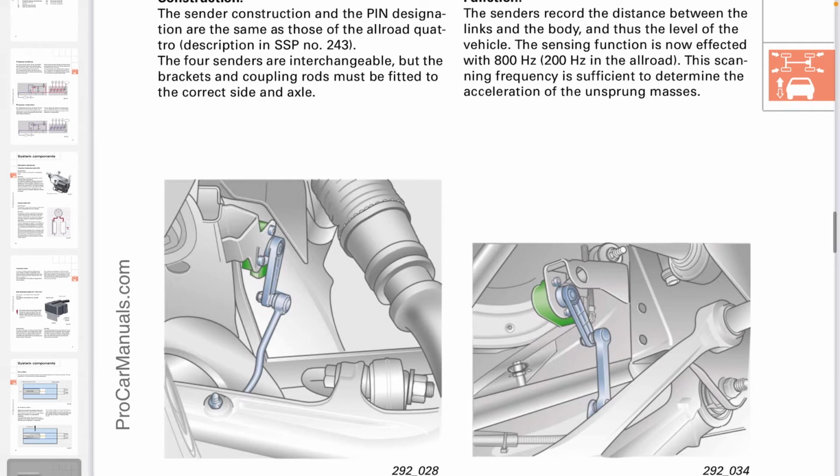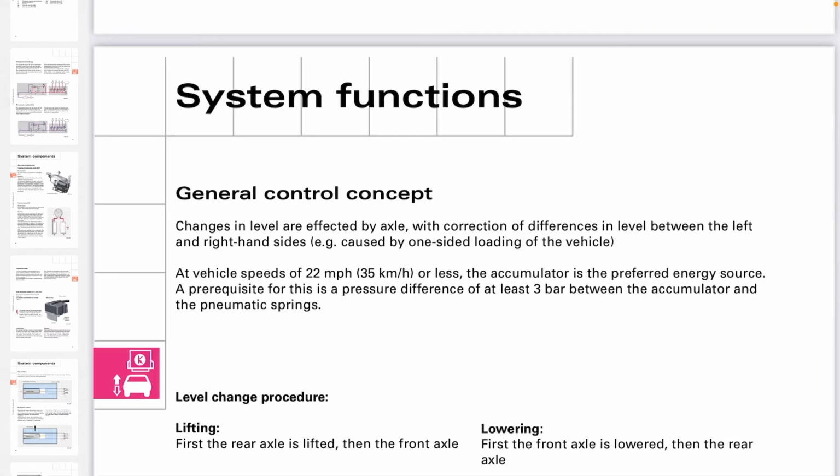Even so, the Audi Allroad has a good ride comfort, and that's it. Lift one and everything else about raising, lifting, and lowering have the same specifications, and speed as well. Above 35 kilometers an hour, if you are in lift mode or Allroad mode, it will go down to somewhere in the middle between comfort and Allroad.